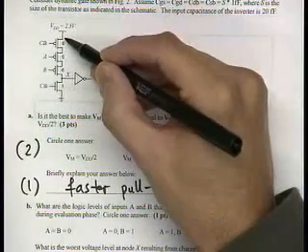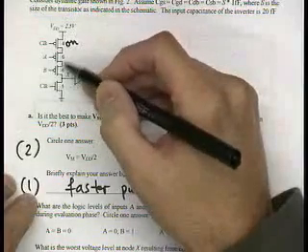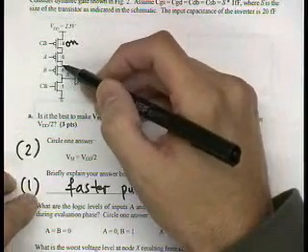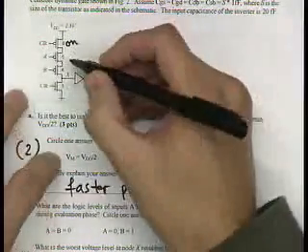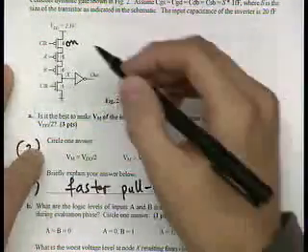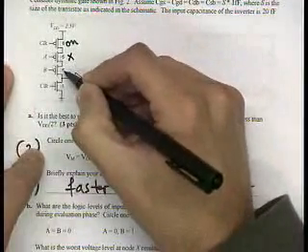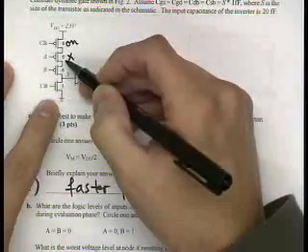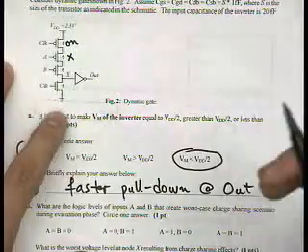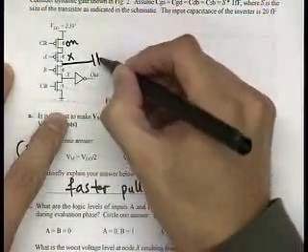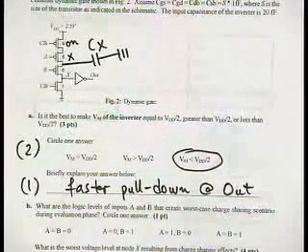So if this transistor is on in the evaluation phase, that means you have to figure out the maximum amount of intermediate capacitance that you can expose to the output. And in that case, basically the winning combination is that this transistor is off and this transistor is on. Because if transistor A is on and B is on, then you simply have a pull-up. So no charge sharing, right? So in this case, you want to expose this capacitance Cx. And so this is the answer then.